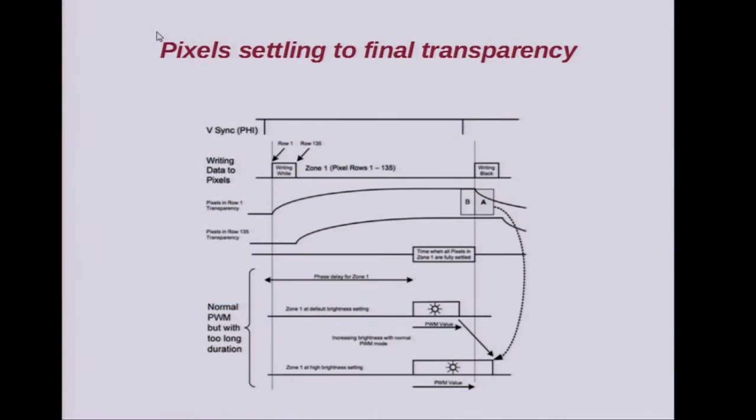And you do that with LEDs by varying the time that the LED is turned on. So now we can start varying the length of time. Obviously, if you lengthen it too much, now you're back into illuminating it while the values are changing. So there's a lot of little tricks played to find the absolutely correct time to illuminate the pixels.